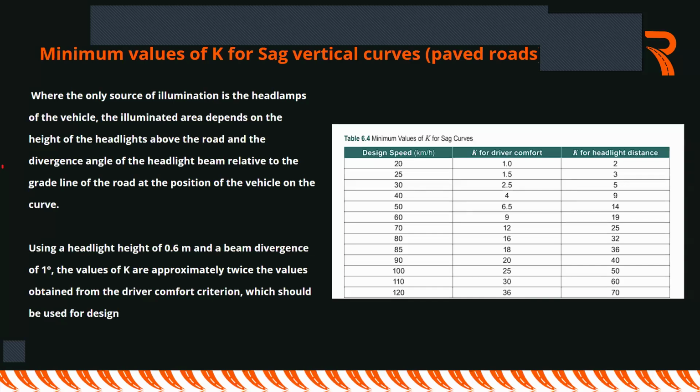Because you will always notice that it is more often that you find the drainage structures located along sag curves. Why? That is where you naturally find waterways and you find provision for outfall.